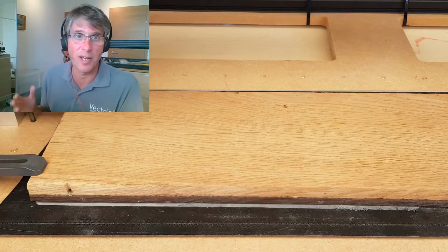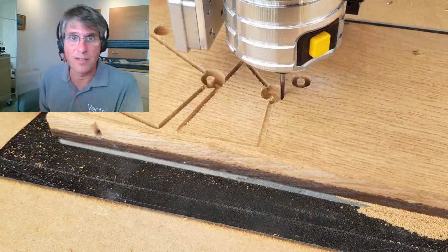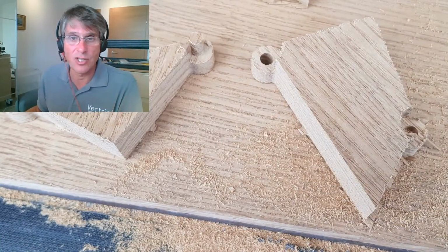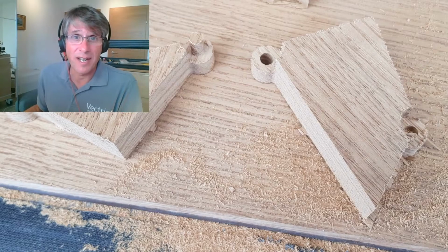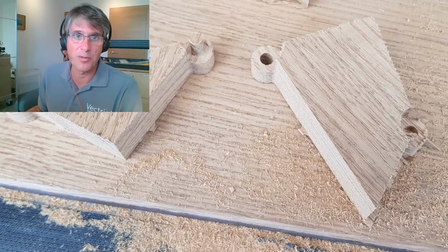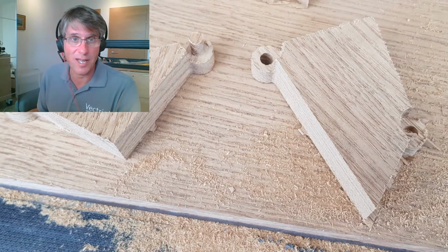And the result really is that we took our piece of oak, we're able to cut our pegs and our pockets ready for the cutout pass and the final hole drilling for the hinges. The eagle-eyed amongst you are going to know that although I said we're going to have to come back and think about the little filleting issue on this profile, I didn't do it, did I? So you can see here there's a little tiny fillet on the edges of those hinges, and that just makes the fit as you adjust and bring the corners of the parts into those gaps. They do not go quite nicely, so that's a bit of a shame.